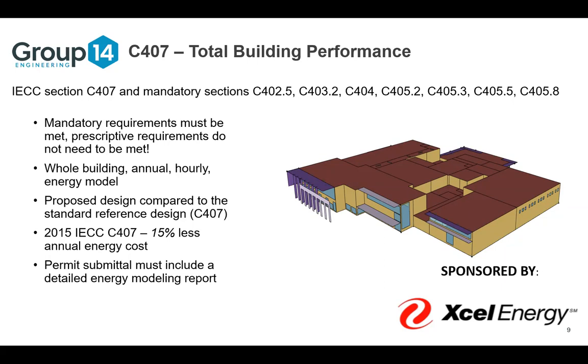Or we have a lot of project teams say, we don't want to do continuous insulation. We only want to put insulation in our studs. And so we can find ways to offset some of that increased heating and cooling energy use for the lesser insulation by reducing lighting power density or having a more efficient HVAC system.